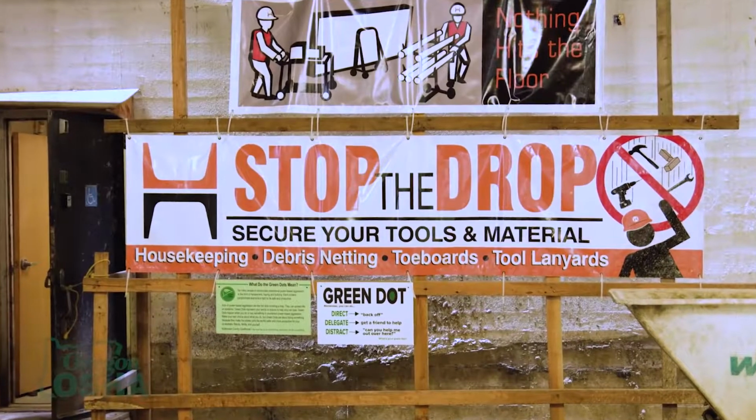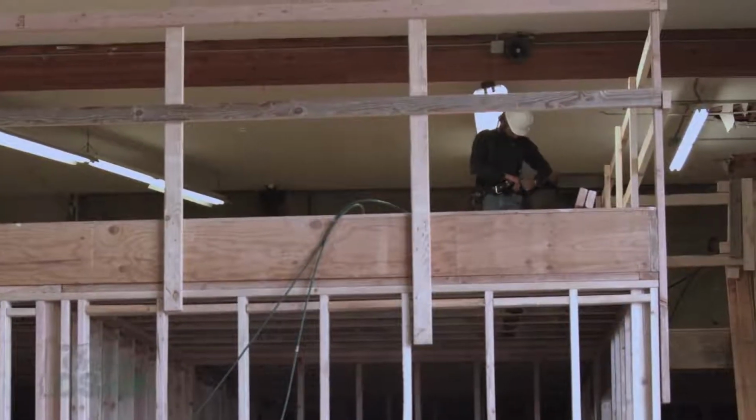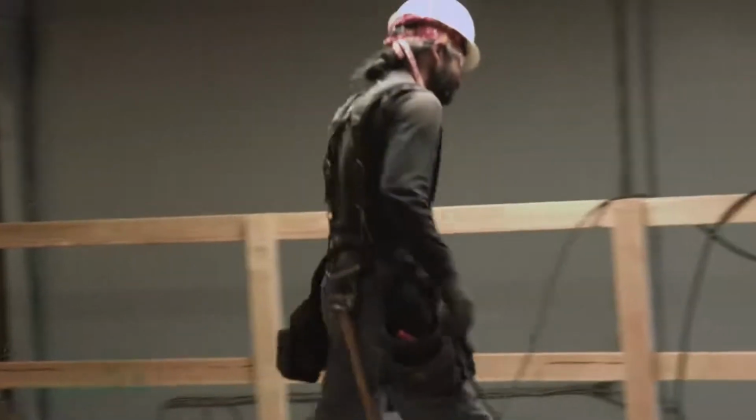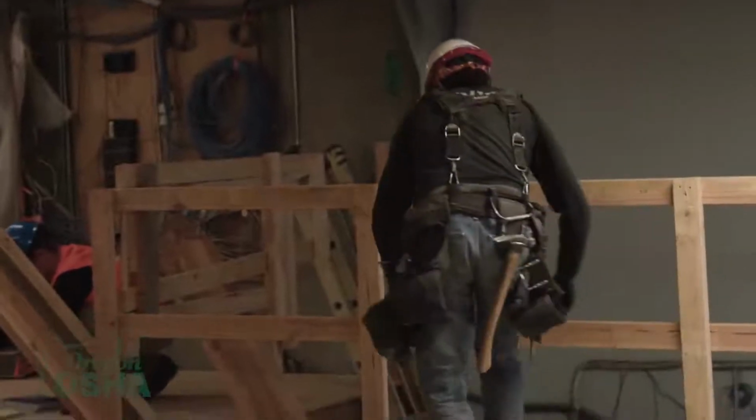So there's several ways that an employer can protect their employees from falling object hazards. The first one is eliminate the hazard altogether by not allowing employees to be underneath areas where materials can fall from above. So as long as there's no employees underneath, there is no exposure to a hazard and you don't have to worry about it. But if employees do need to work underneath, then we want to take into consideration things like if you're using a guardrail system above to prevent employees from falling to a lower level, that we have toe boards installed to prevent tools from accidentally being kicked over the edge.